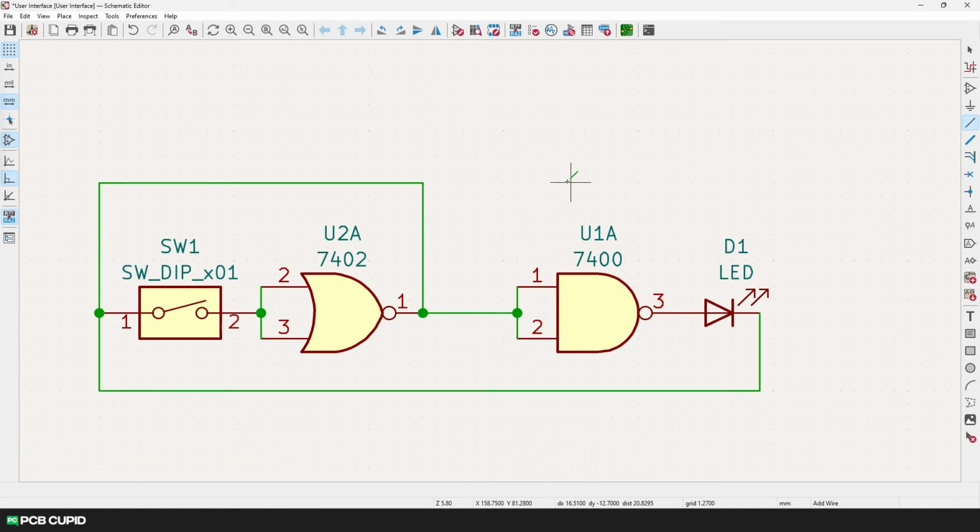And now if I zoom in and zoom out, you can see small points where our cursor snaps onto. These are called grid points, which will be of great help when connecting two components together. So we don't have to fiddle around to connect them properly. And you can see the distance between them over here. And finally, the mm represents the millimeter. That means all the values that are shown here are in millimeters.